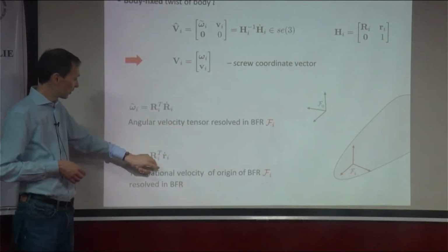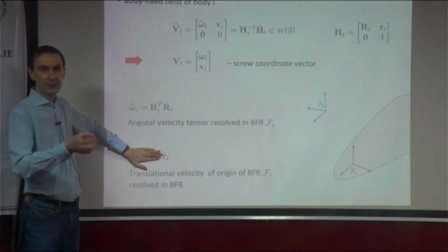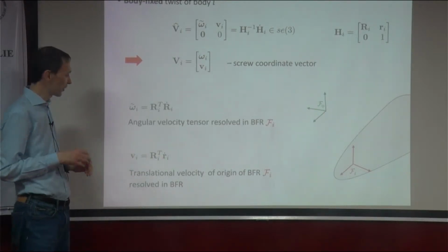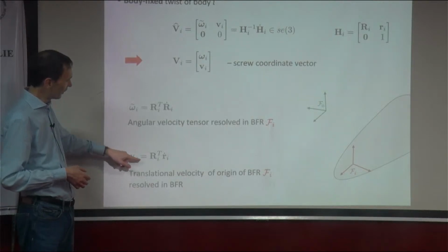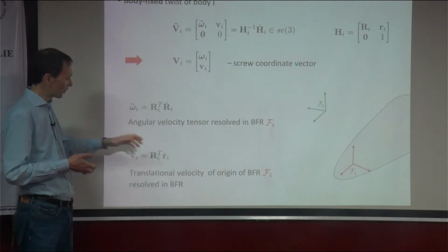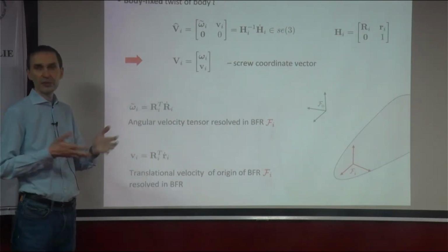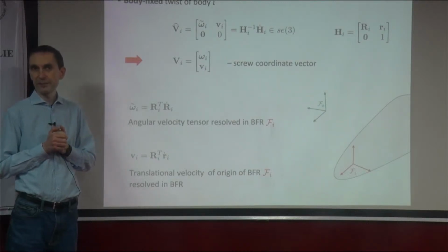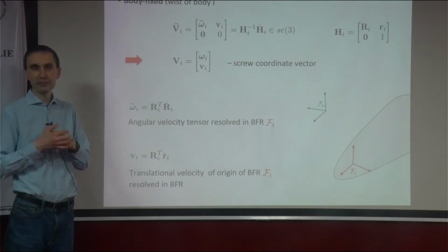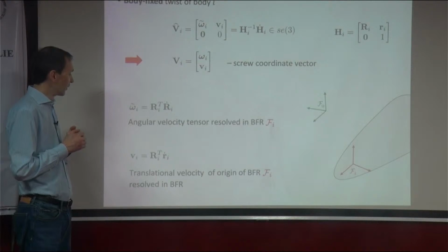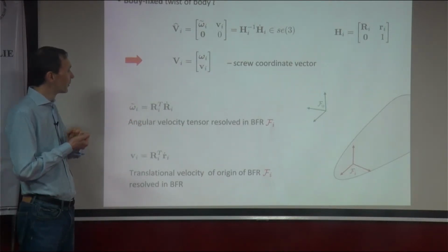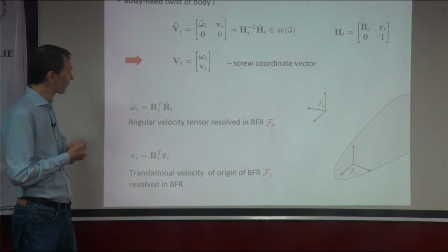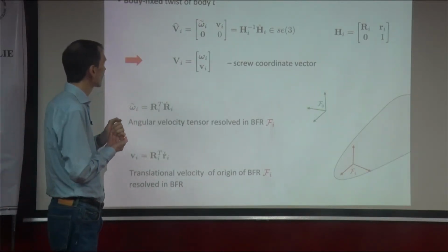And so R dot would be the linear velocity represented in the space-fixed frame. And this, we call it little v: the rotation matrix transposed times R dot, and that's the velocity in the body-fixed frame. Of course, the same velocity, just different representations. Now, this is all what you learn in, I don't know, mechanics. The funny thing, or the good thing, and there is much more theory behind why this happens, is